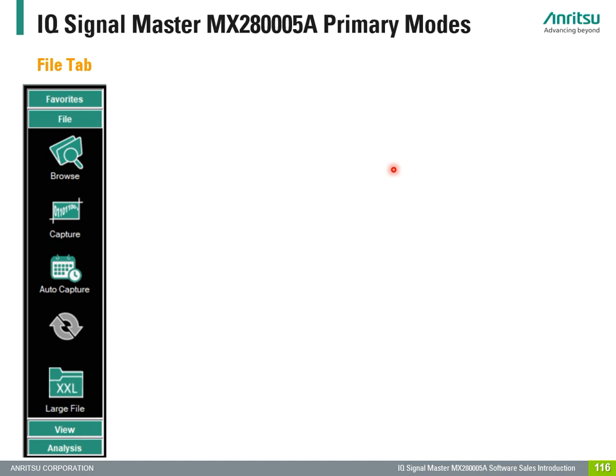Up to now, this was the hardware-based side of IQ capture and replay. Usually, the gained IQ baseband data occupies large amounts of memory, and this is putting a lot of stress on the user while handling such large files. If your system is currently, for example, set to a FAT32 partition, you will have no problem transferring files if their size does not exceed 4 GB.